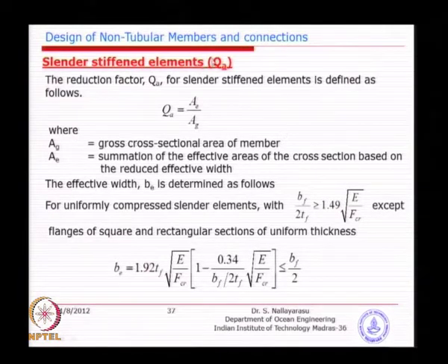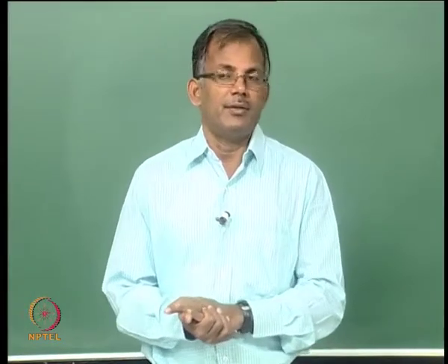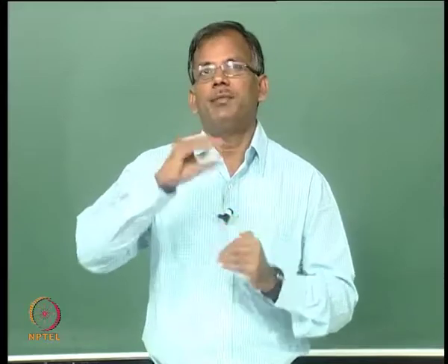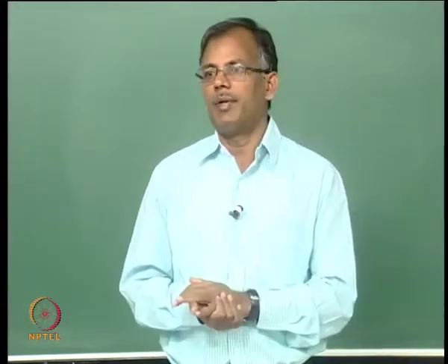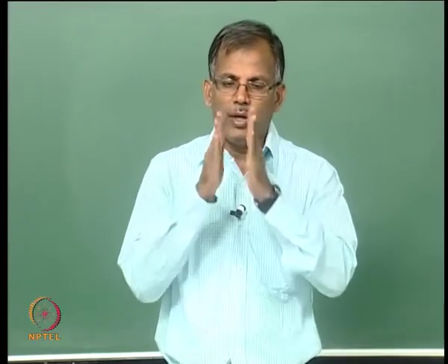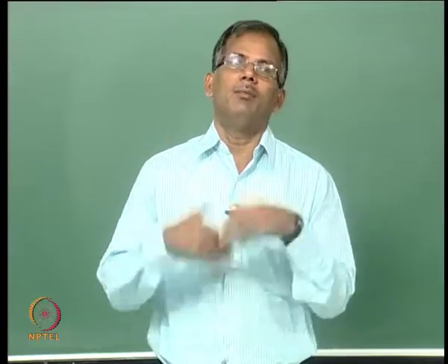For example, many times we want to make the girder very deep, because we want more moment of inertia, thinking that by simply shifting the flange away I will get more moment of inertia. That will be correct, provided you have sufficient thickness for your web, otherwise the web will become slender.